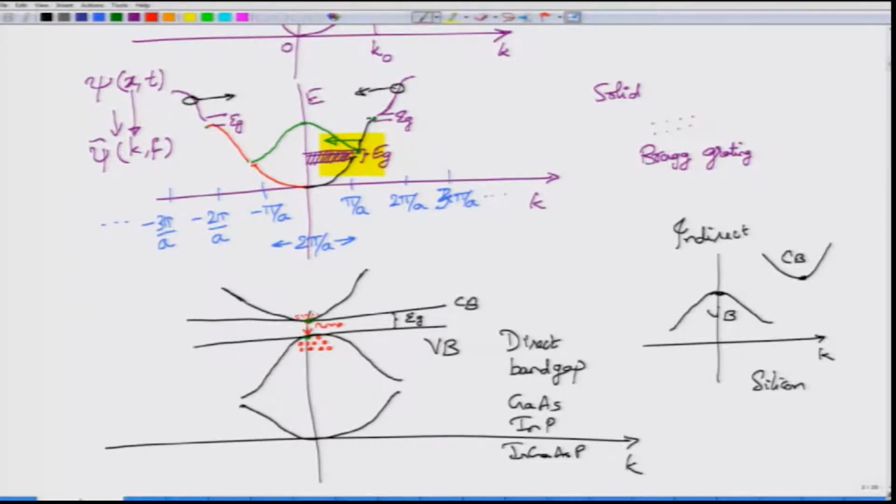If you did not have exactly the top level transition, maybe the electron sitting here might want to transit down here. If I blow this up and show it to you, it looks like this. So, the electron that is sitting here is making a transition onto the hole here, in the process generating a photon h nu. Please remember, this is a highly exaggerated picture. This is not the same scale as this one. I am just showing it because I can't draw an arrow and show it to you in a nice clear way.